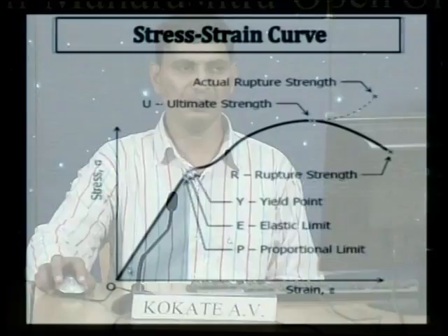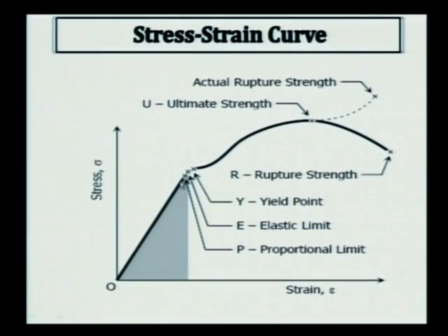If you plot a graph of stress versus strain by increasing the load step by step, stress increases step by step, and strain also increases. Stress and strain are both increasing, directly proportional to each other. The graph is a straight line, and Hooke's law is valid or obeyed. If you increase the stress above the elastic limit, then a small increase in stress produces a major change in strain. There is one point, called the yield point, from which, without an increase in stress, strain increases rapidly. That is called the yield point.